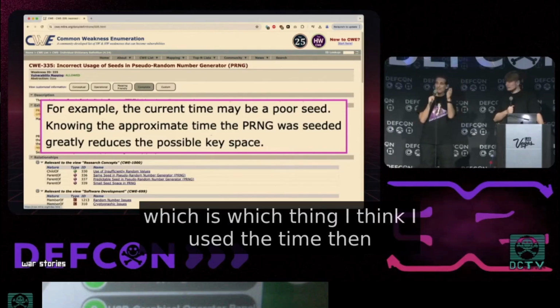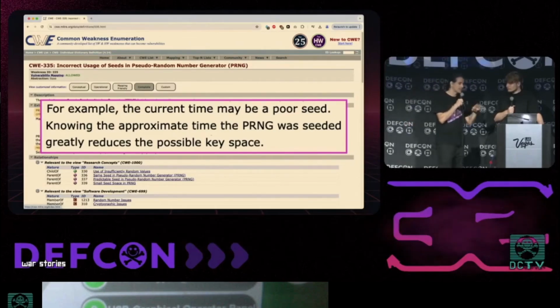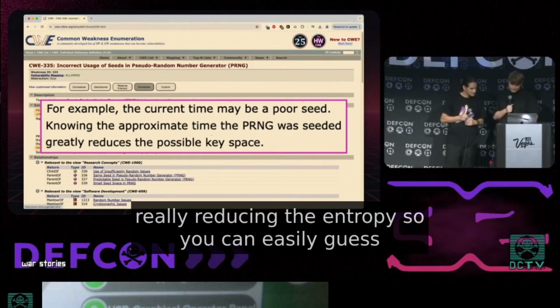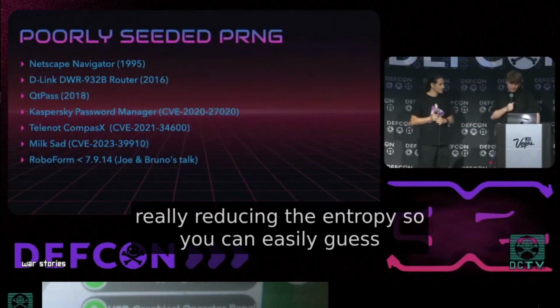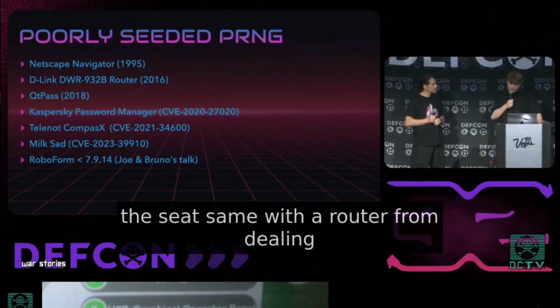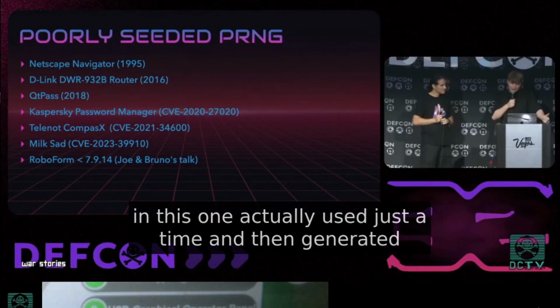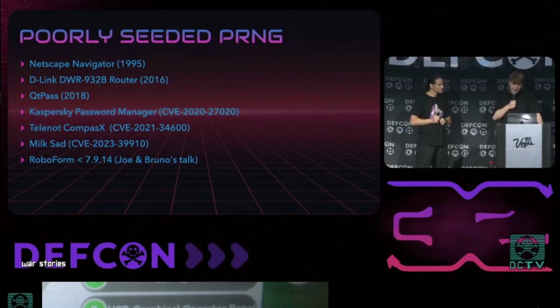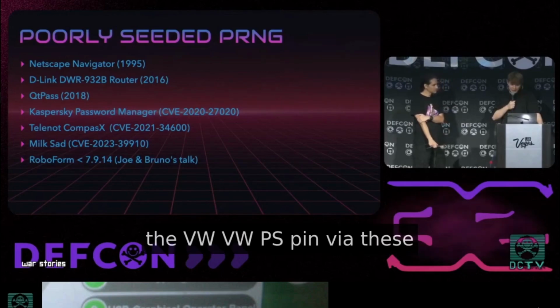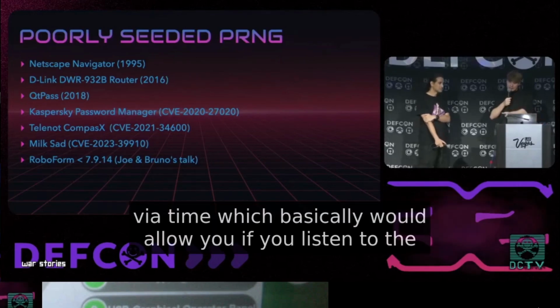So imagine you have a little device with a photodiode, a photosensor, on you, so that whenever someone points their phone camera at you, you get a little vibration. Because you can just measure for that frequency of light and for that on and off pattern. And now you can know when someone points their phone camera at you before they're even recording. You can see that sort of rectangle, that's exactly the same pattern. That means I could just make all of you vibrate right now. How fun would that be? So, separate project, we'll do that another time.